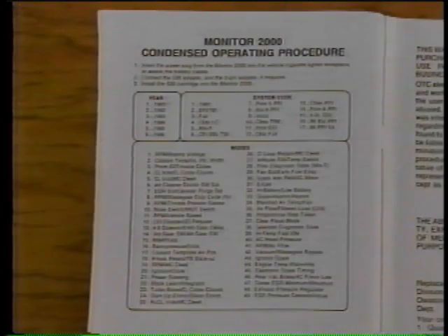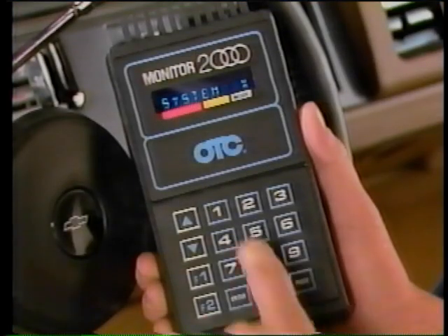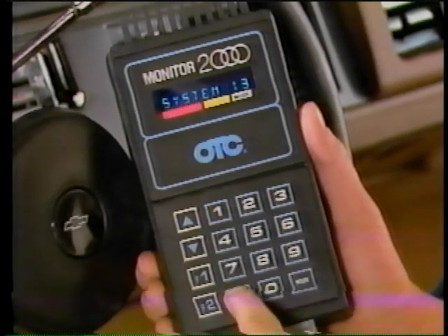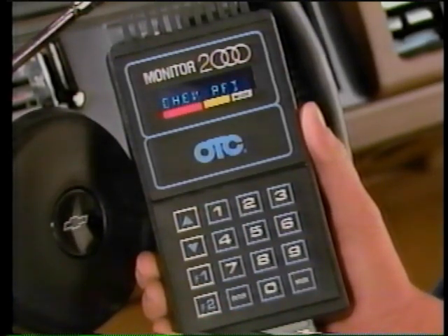Now the scan tool will ask you what system the vehicle you're working on is equipped with. It's very important that you enter the right system into the tool. Otherwise, your test results will be worthless. If you're not sure which system is on the vehicle, note the 8th character of the VIN. Then look in the scan tool instruction manual. When you find your application on the list, it will give you a code to enter on the keypad. After you enter the number, the name of the fuel system you selected will scroll across the display. If the system you selected is incorrect, enter the right number on the keypad, then press enter.